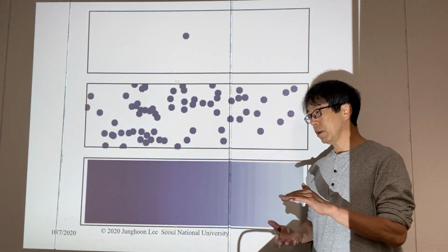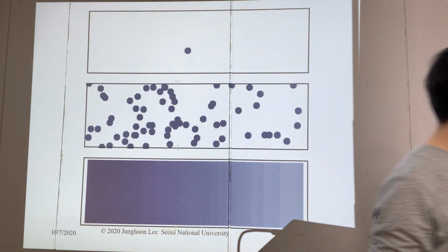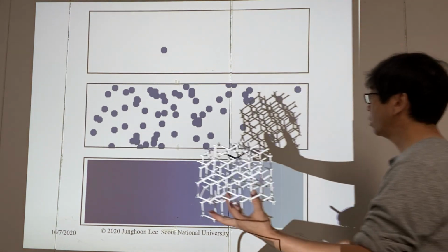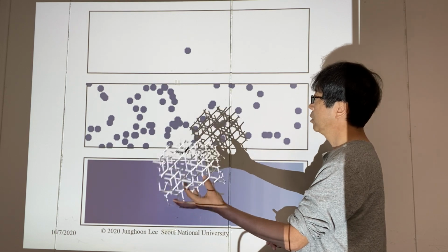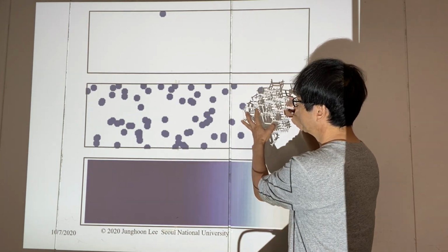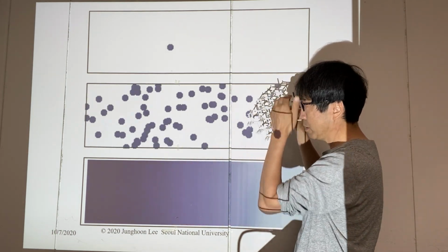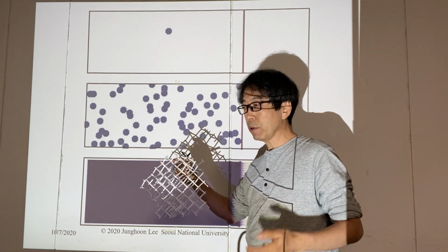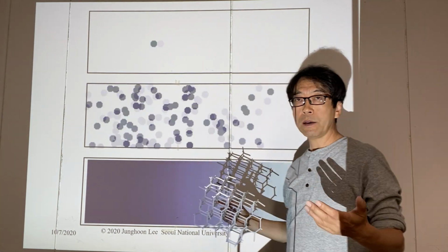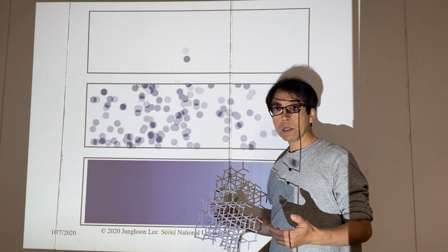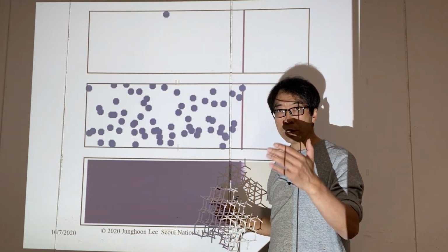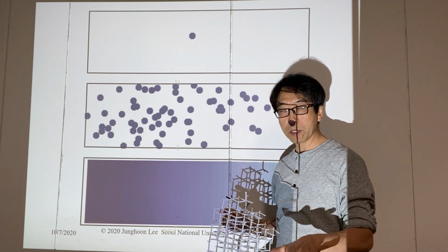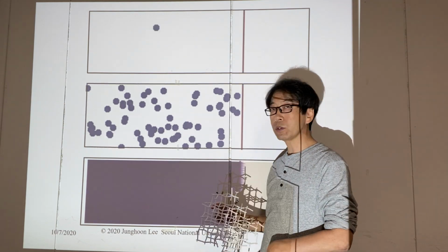So you have a crystal of silicon, and on top of the silicon, you would like to deposit some impurities by certain means, which I'm going to explain. It could be ion implantation, it could be furnace deposition, it could be something else, spin coating maybe. Spin coating is also possible.